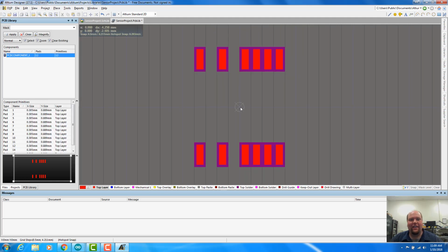So that actually set the 0 reference. If I click here and I look up at the x and y coordinates at the center, that is now 0, 0. So this is going to be negative, negative, positive, positive, and so on, right? And the cool thing about this now being the center of my grid is, regardless of what my x and y grid snap was, when I Control V this thing, it can snap right to that center. So that's a nice little way to cheat and get a center.